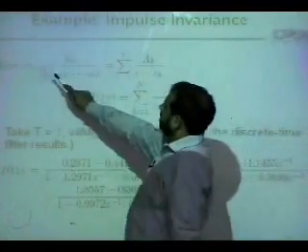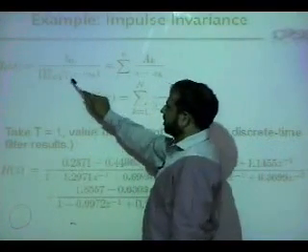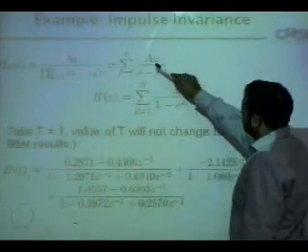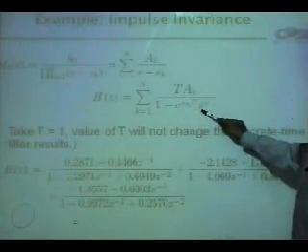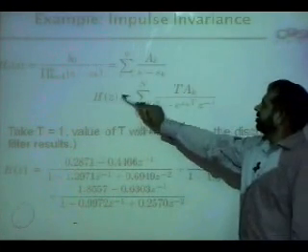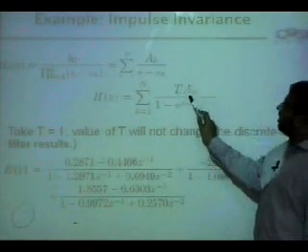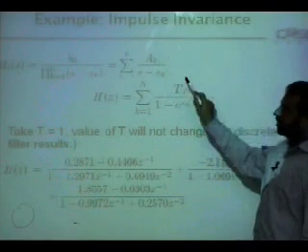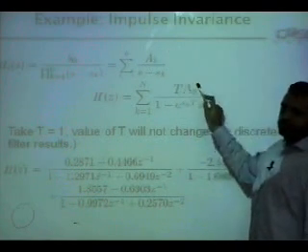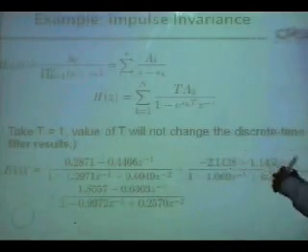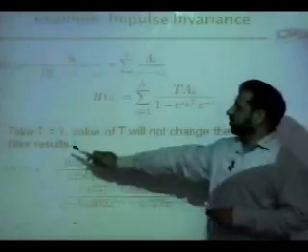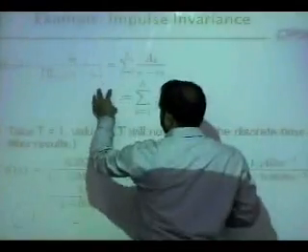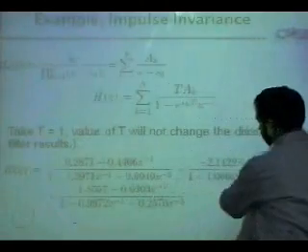Here you have H_c(s) with 6 poles, and this is translated into H(z). Every s_k appears here, with the same polynomial expansion, the binomial expansion, and the same constants. You need not even change them. Then you combine, keep T equal to 1, and translate H_c(s) into H(z), which is written here.